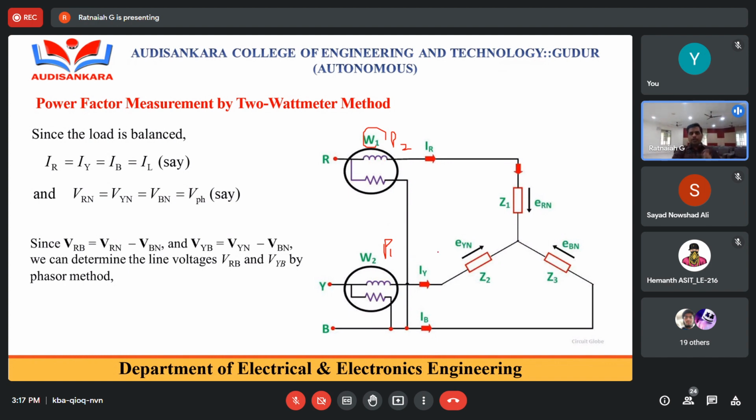So the nature of the load always depends upon the type of the impedance. If the impedance is R plus j XL, then we can call it an RL load, or inductive load. If it is a combination of resistor and capacitor, we can say it is a capacitive load. But the total load depends upon your connections, that is, P1 and P2. That is your assumption. If P1 is more than P2, then it is an inductive load.